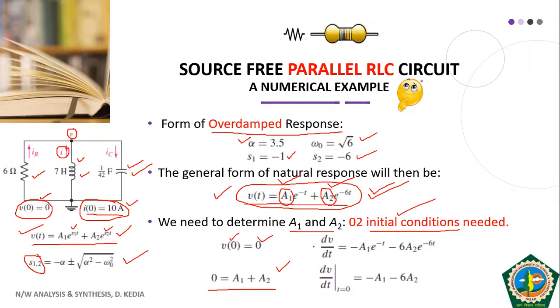So what we will do now, we will differentiate this equation. This step we did not have in RC and RL. This is the new step that we will carry out in this RLC circuit. We will differentiate our general form of natural response. Once we do that, we get dV by dt. Then a1 e raised to power minus t differentiation, we get minus a1 e raised to power minus t. Then the second term differentiated give us this one. And it is quite evident and very simple thing. You can easily make out how we have arrived at this thing.